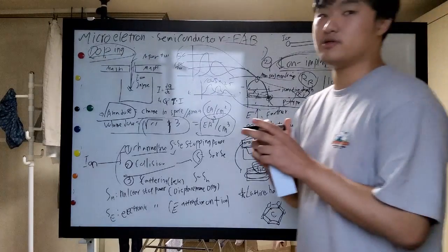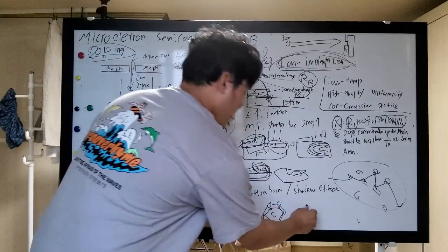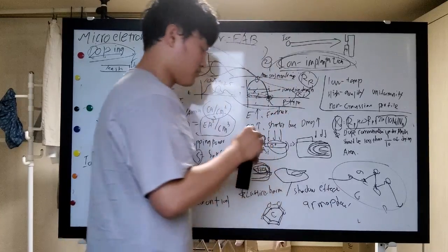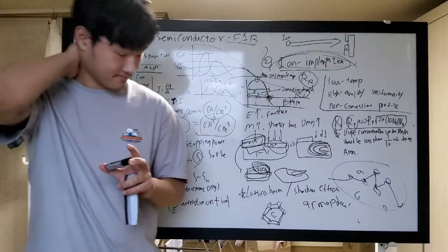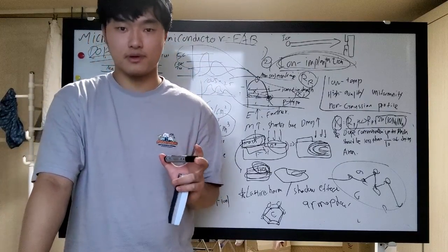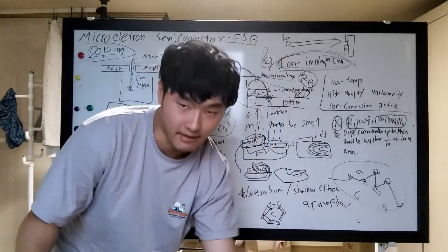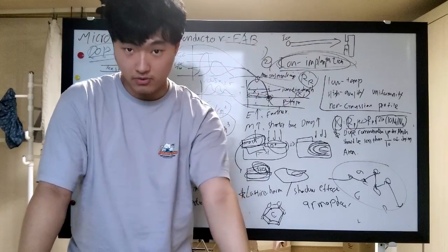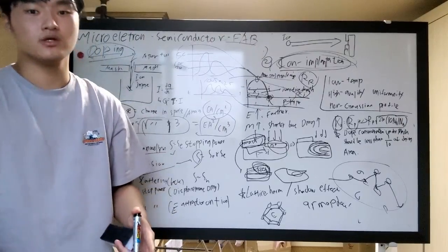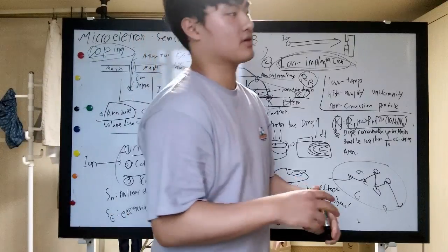And here is one thing. Of course, we talked about how silicon dioxide is amorphous, which means it has some holes and gaps, so there is some probability that the ions can pass through the amorphous layer and penetrate straight into the silicon. So in a bad case, the doping effect will happen even under the mask.